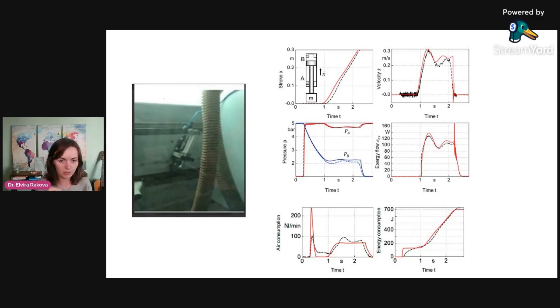But what is extremely important here is that the piping and compressed air system is an extremely complex thing, right? When we have piping that is used as a passage through, we need to have maximum capacity, maximum sonic conductance, so that everything just passes through this pipe. When we have an application with a valve, where before something happens on the end side the volume has to be filled, and then it goes to the exhaust, this is where the sizing is extremely important.